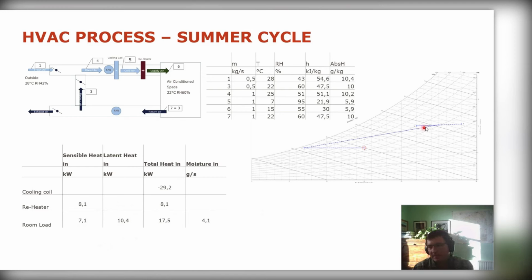So we'll talk about the ratio between sensible and latent heat in a second, but let me just highlight something else that I wanted to show on this graph: why do we need the reheat in this case? If we said, well, let's just cool down to this point, 0.5, and then supply the cold air straight into the room. Well, you could potentially, but the problem is you would be providing a lot more total cooling, so the temperature would start to drop. You will be freezing people in the room. You say, okay, well, in that case, let's just reduce the flow rate. So we're still providing at the same temperature maybe, but we reduce the flow rate. The problem in that case is that, well, in terms of the total cooling you provide, it will be adequate, but you will not be providing as